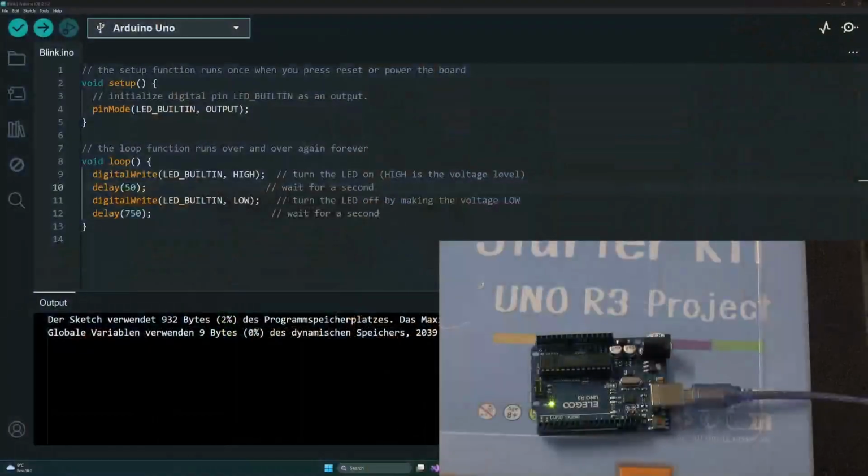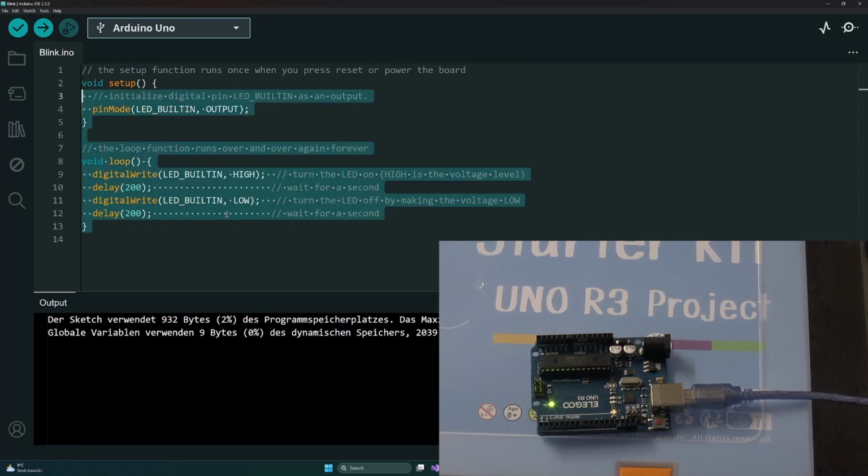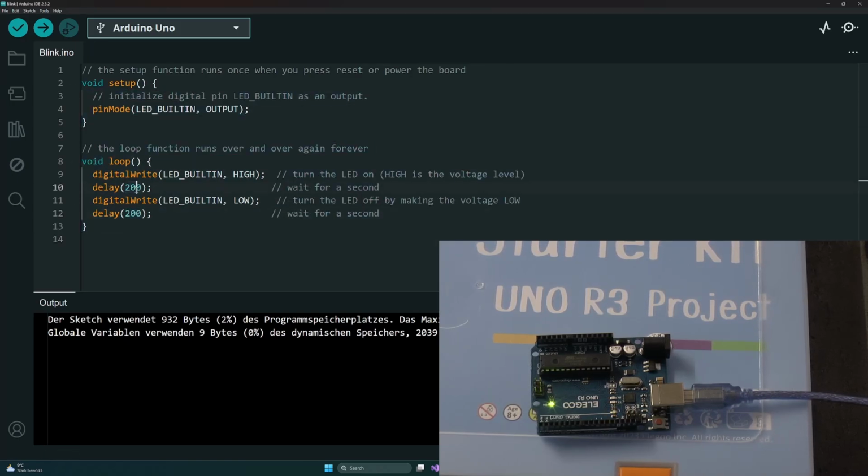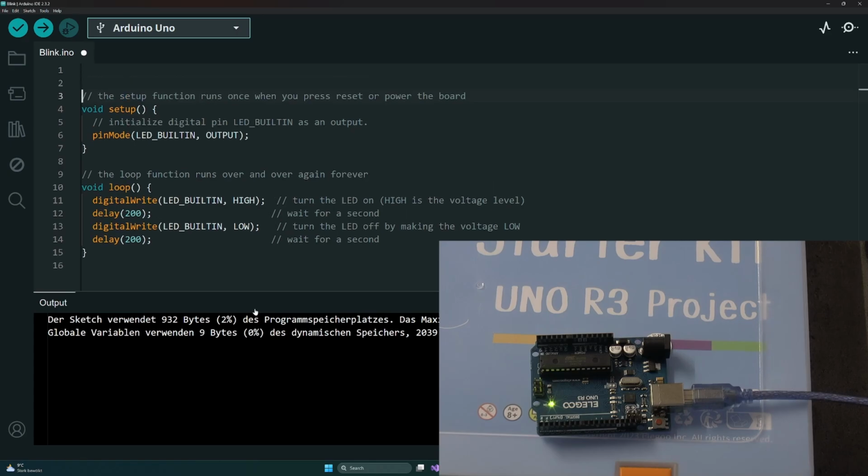software of this code. Now, what I want to do is I've promised you that we're going to improve it. Basically, how can we improve that? Let's jump back to the original use case of just having some normal blinking, so same on time as off time. Now what we can do, similar to how the Arduino uses this built-in LED, is use the same technique to define ourselves constants or parameters of our application.